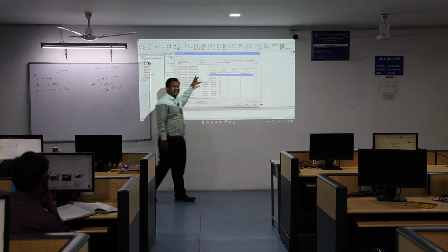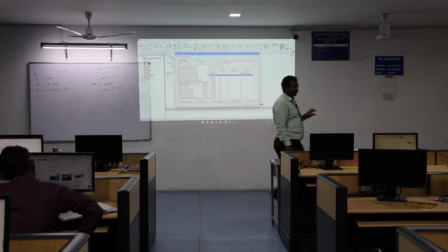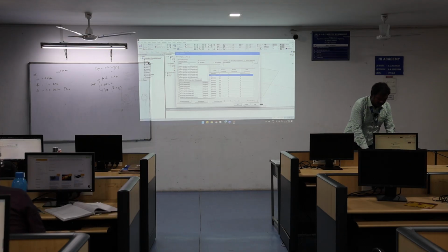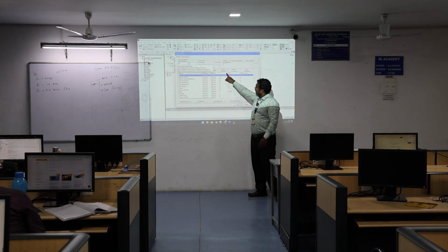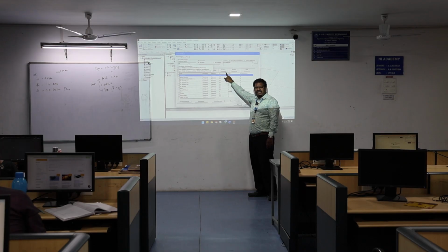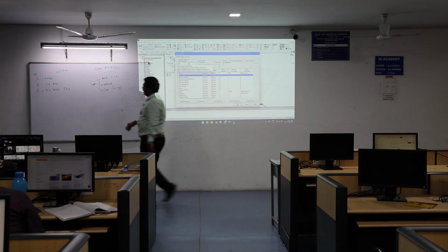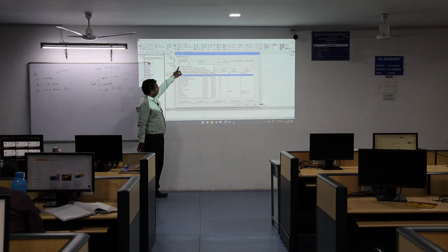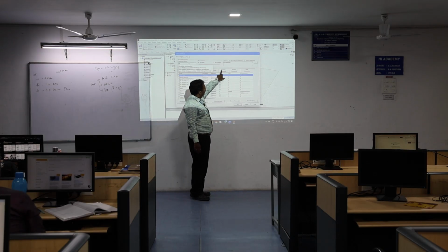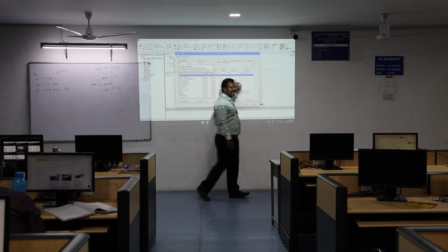This is an LCD PCB component, but I am using FR4 also. Here, type FR4. A variety of FR4 epoxy is there. Here the relative permittivity, that is called epsilon R. I am choosing epsilon R as 4.4. My material specification is 4.4. So here, FR4 epoxy, and the relative permittivity of 4.4 is the chosen one.